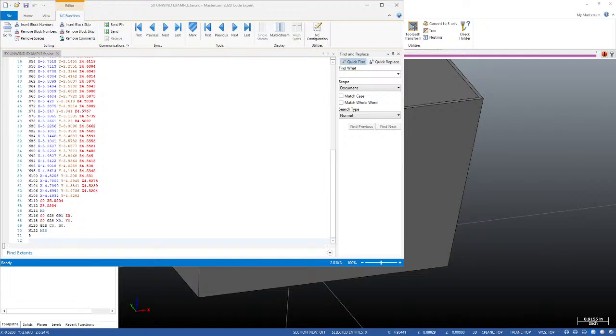We're always going to have at least 2 vectors for the entry. So 1 vector for the entry start point, 1 more vector for the start of the cut. But now you notice we get a point here, we get a point here, and we get our exit point here. Unfortunately, there's really no way to filter out the extra entry and exit points in the toolpath. If we're using entry exit, we get 2 extra vectors, end of story.